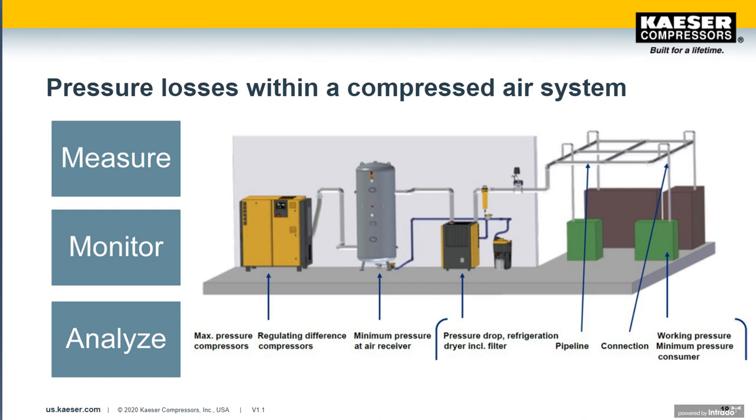In the real world, we're talking about up to a 10 psi drop in the main header piping and up to 30 psi in those last point of use connections. Werner mentioned that dirty 30. So if we add those two together, that's another 40 pounds. So instead of 104 psi, we'd be more like 70 psi at the point of use. So things that you want to consider in your design. Now I'll hand it back off to Werner.